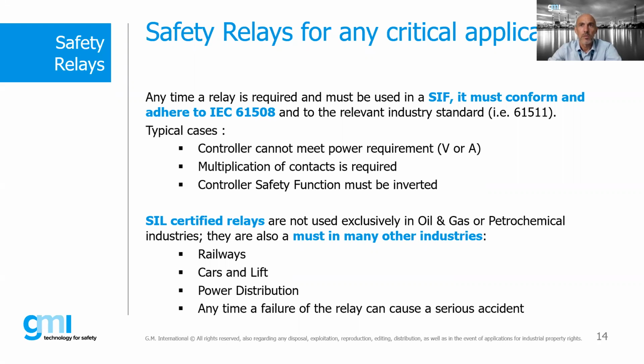So typical cases are where you want to stop or start motors in a safe manner, or you want to open or close a valve, and so on. That is the typical case for using a safety relay.